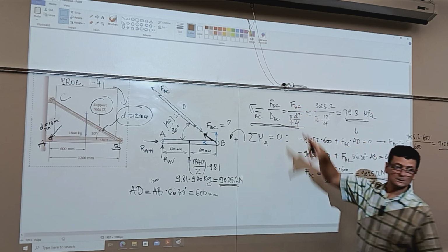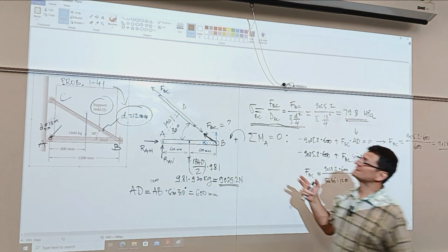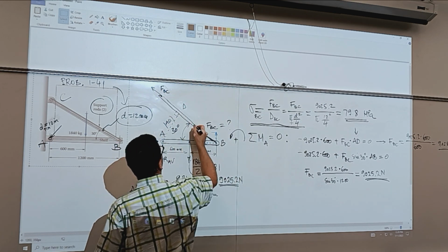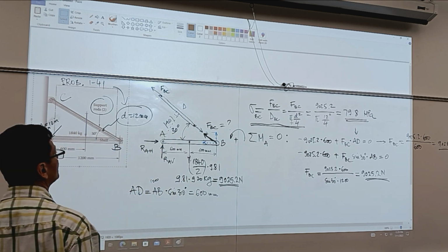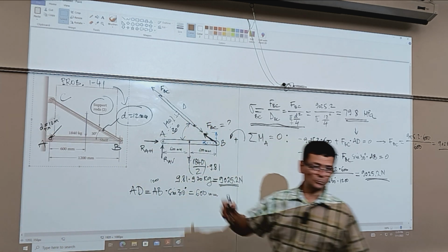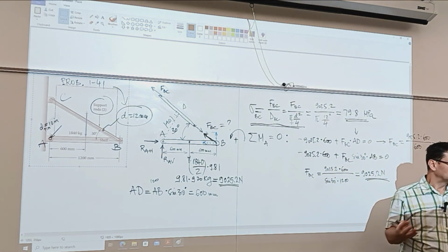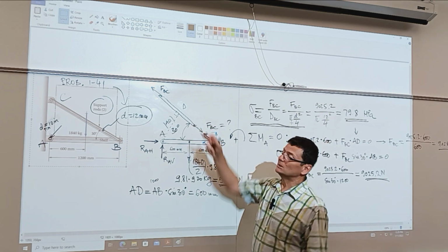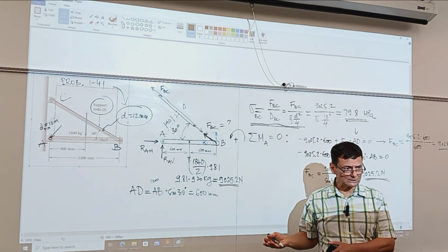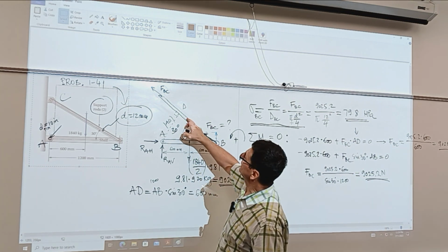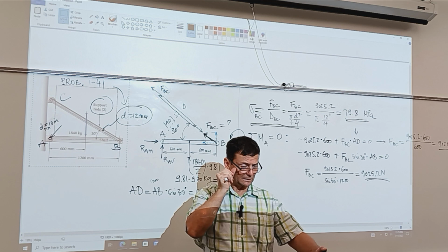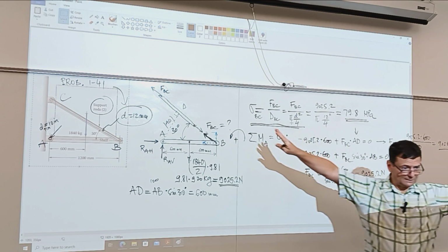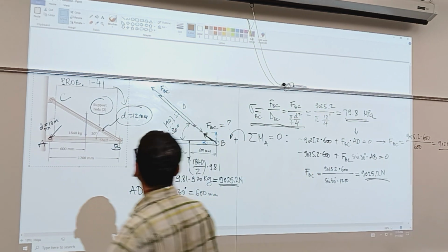This was the new part. You take the area divided by, again, this is direct tension. Assume even the two-force member, recognizing a two-force member. So we've got a problem solved. If we know the material of the rod and we know its tensile properties, then we can declare the design safe. Okay, so I can relate to yield strength. I can relate to ultimate strength. This one here, if it yields once, no hard feelings. Remember, the airplane, the wings ended up a foot higher, and they continue to fly it.